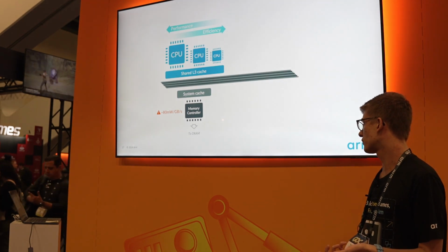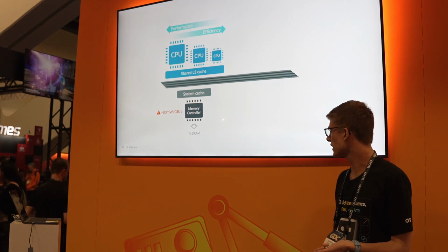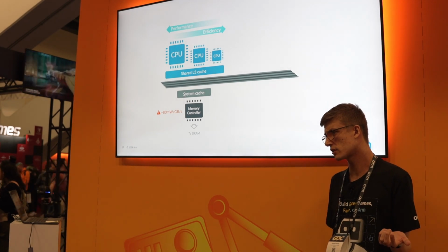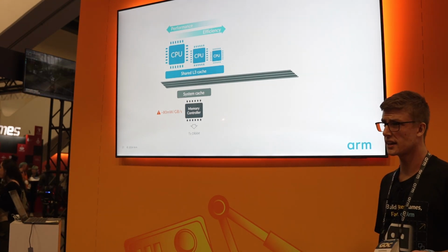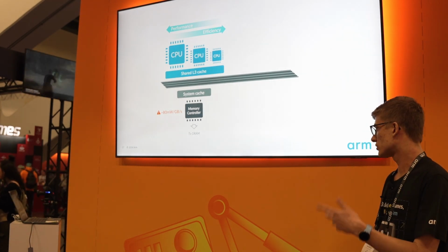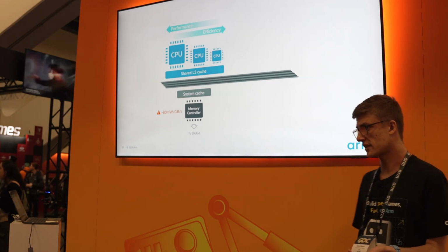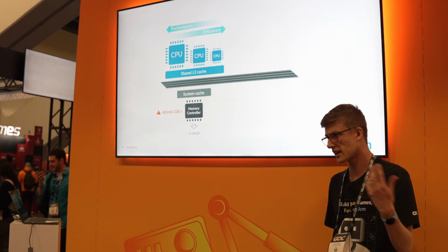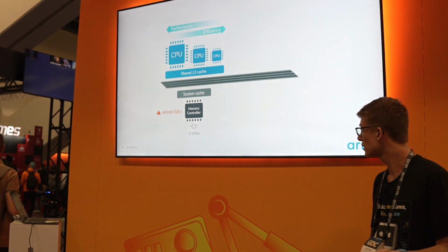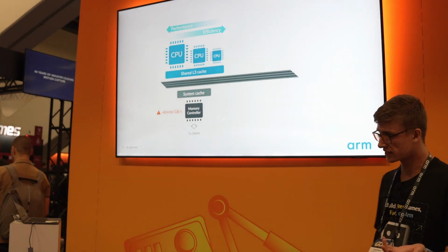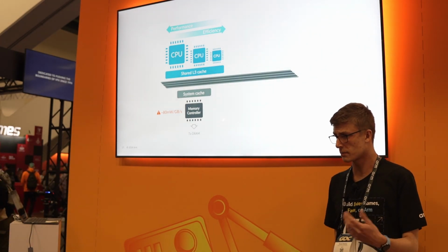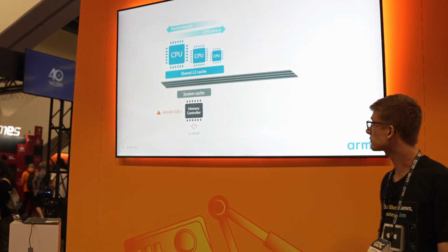The power consumption for a memory access is 18 milliwatts per gigabyte per second, approximately. And so whilst you might see in specs there are sort of 60 gigabyte per second performance, this is not sustainable. It's only for bursty workloads. So you can find even using 25 gig a second, that's half your power budget gone. So bandwidth is a massive constraint here.